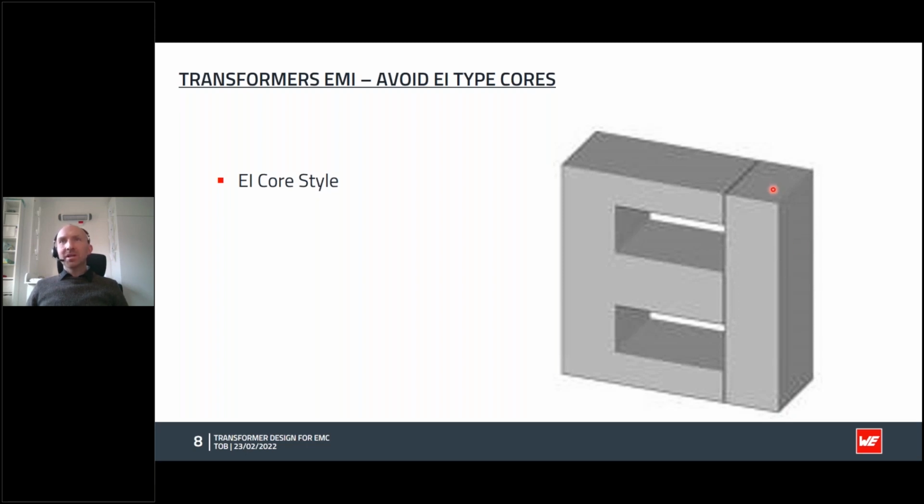The air gap is basically the main storage part for the energy that we want to transfer on the off time. On the on time, the energy builds up in the core, but is stored in an air gap. So we need to create an air gap in all inductors, and definitely in a flyback, which is not technically a transformer, it's a coupled inductor because of this air gap. But flyback is a very popular topology, and so we need an air gap.